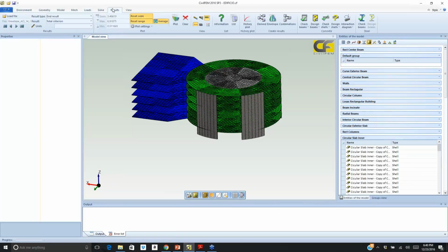There are different methods of designing the reinforcement for the slabs. Just as we stated in the beams and columns reinforcement design analysis, the same options are available for the shells representing the elevated slabs and also the walls. Here are the different methods that are applicable to calculate the reinforcement for capacity and to avoid or minimize cracking.